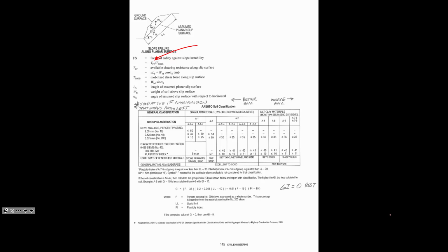So you can calculate what the shear strength is. You can calculate what your mobilized shear strength is, and do your math and come out with a factor of safety. Like I said, we've got a problem or two that's just like that you can go through. Those start to take a little too much time, if you ask me, because you've got to calculate areas and calculate weights and all that kind of good stuff.